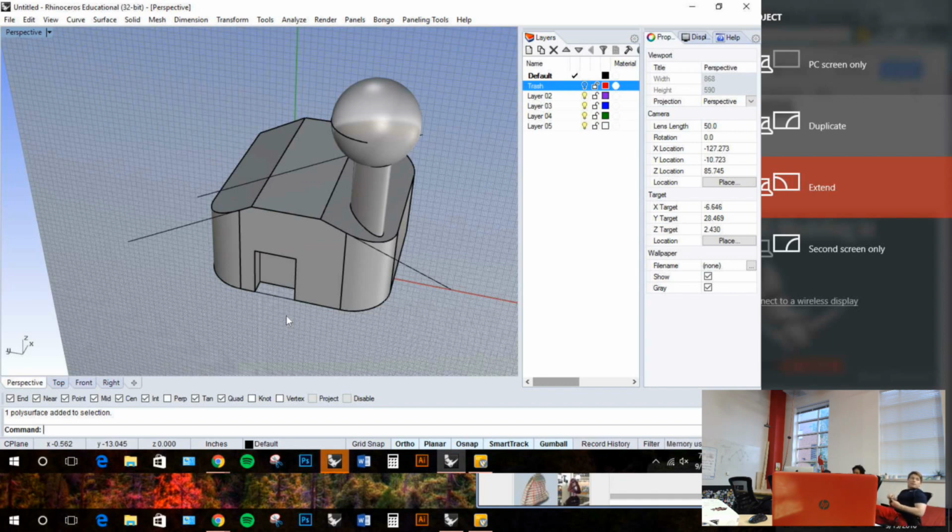Hey. I've been having a lot of trouble with drawing the lines. A lot of times they're just in random directions. Okay, so what it wants to do is draw the lines on this surface on the bottom here, and you can move this surface around. This is called the C-plane. So go to View, Set C-plane, and then To Object, and you can click the face of the object that you want to draw on. And so now it's set there, and it'll be easier to draw there.